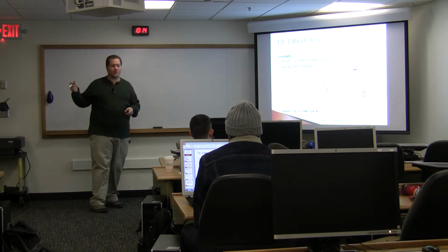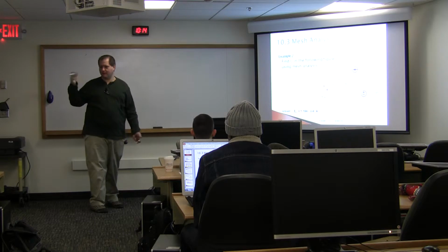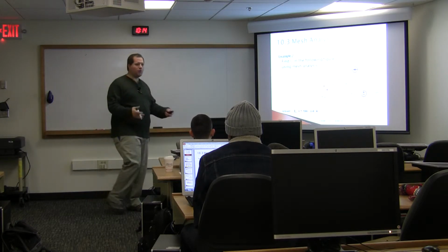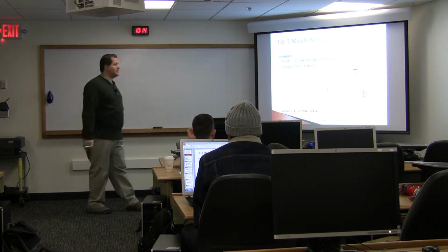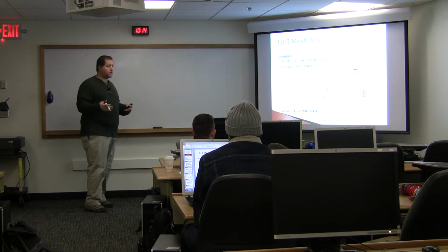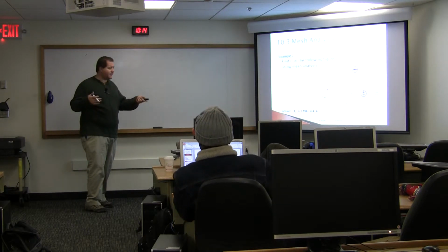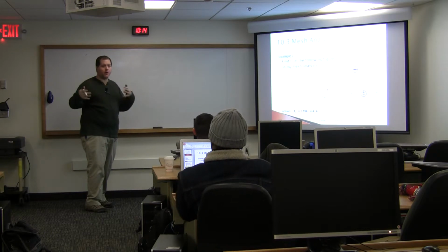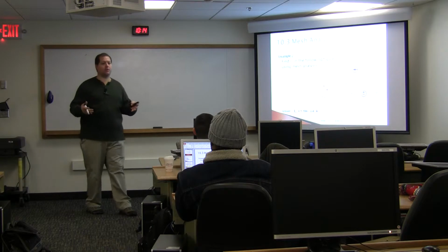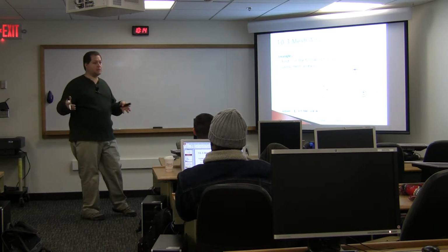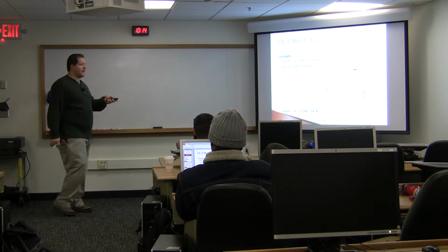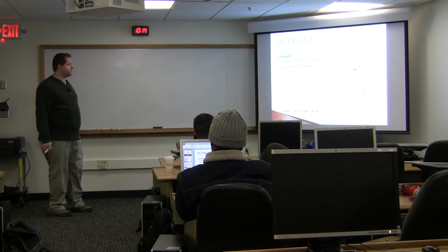You can't walk into the lab and pull a negative j2 capacitor off the shelf, right? So in a real circuit you're always going to know what the capacitance is. However, if you were doing design work in the frequency domain and said, oh, I need this, well, that's the value that makes the math work for my function. You'd better be careful about what omega you're dealing with when you go to choose C. So you may use it in the design part, but not when you're actually building or prototyping.